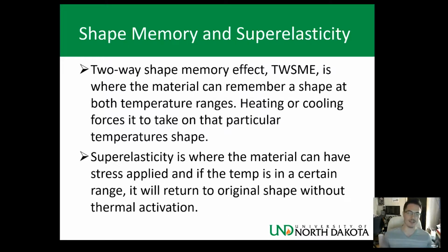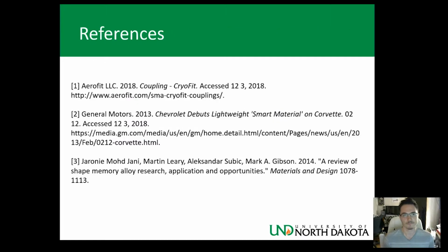So superelasticity, which is the third one, is where the material can have stress applied, and if the temperature is in a certain range, it will return to the original shape with no thermal activation at all. So the heating and the cooling isn't a necessary part of the superelasticity. It will return to its original shape without thermal activation.